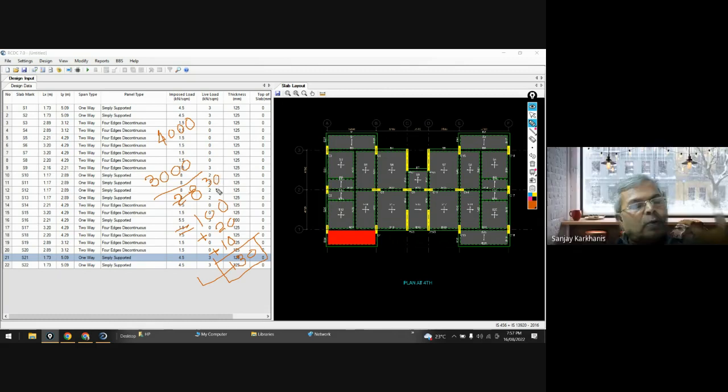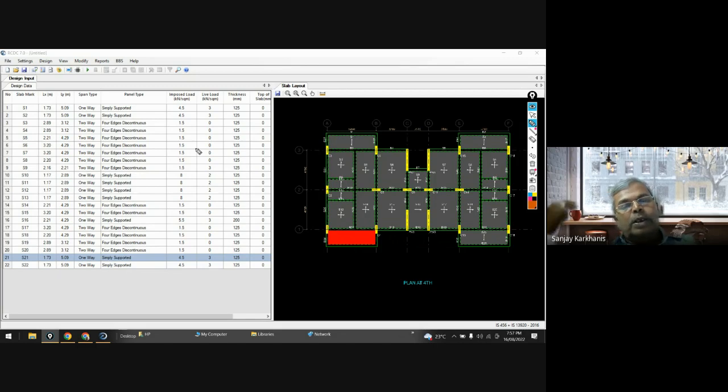142. So that's why you cannot reduce depth based only on strength criteria, because there is another criterion you have to fulfill. Otherwise, the slabs will be subjected to excessive deflection, or cracking at the bottom or cracking at the top, which is detrimental. And that's why, most of the time, we'll be going for setting all panels as non-continuous.